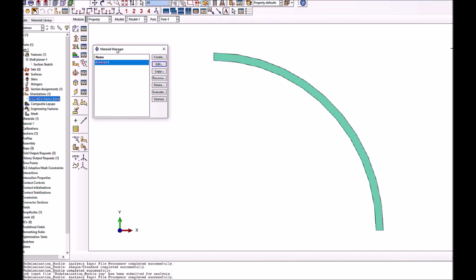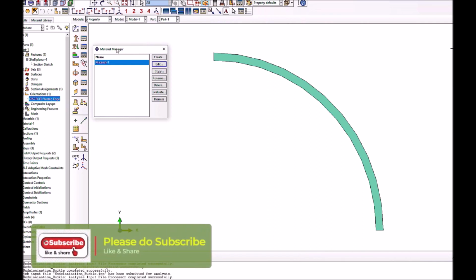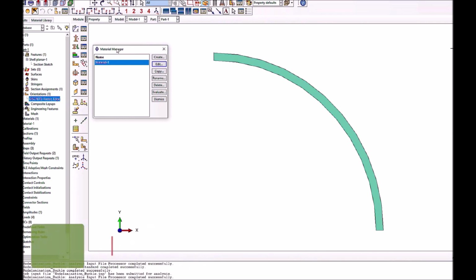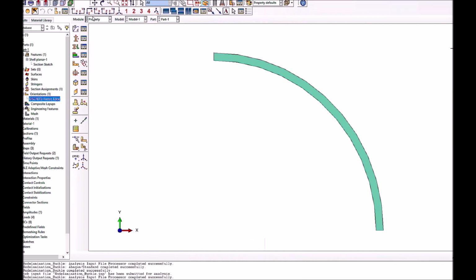If you already have the data on what the properties are in the material after how much exposure time in seawater, then you can use those, and that will give you the values. And you will see that the reduction in the properties, or degradation in the material, can cause a reduction in the implosion pressure. Another thing was defects or porosities and delaminations. So you can have pores, you can have defects. So let's create some artificial defects in this material and see if they really influence your structure.